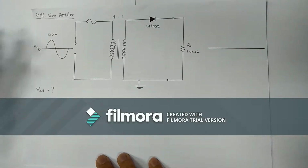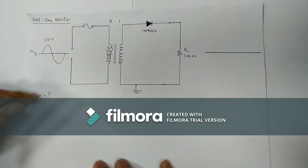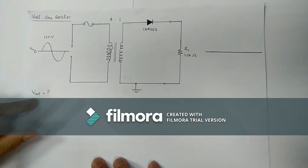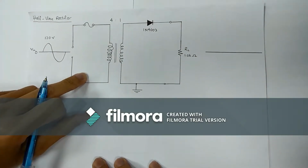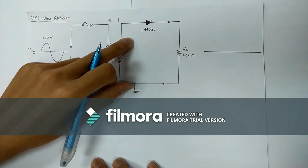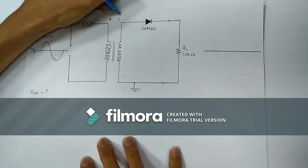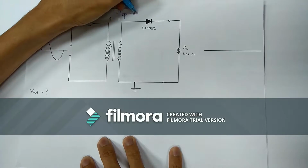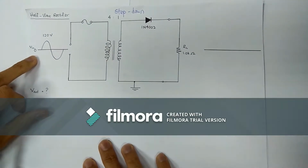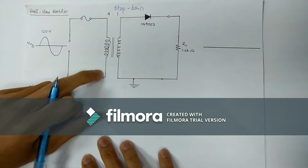Half-wave rectifier. A half-wave rectifier only consists of one diode. In this question, we need to find out the output voltage. We can see clearly that the transformer is 4:1 ratio, so it is a step-down transformer. The power supply to the circuit is 120 volts, so the primary voltage is also 120.